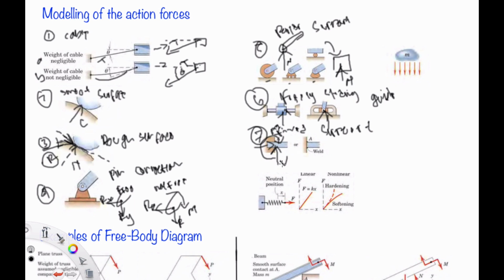it will consist of three forces, where F refers to the axial force, V refers to the transverse force or shear force, and M is the bending moment to prevent any rotation. So the function of the moment here is to prevent any rotation, and it will be the same. It's only different in that the beam is fixed by plugging it into the wall, and here using a weld. They weld the beam to the wall, so it's also a fixed support, and it's really the same.